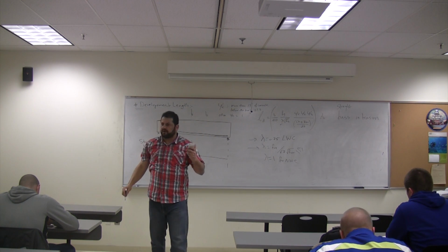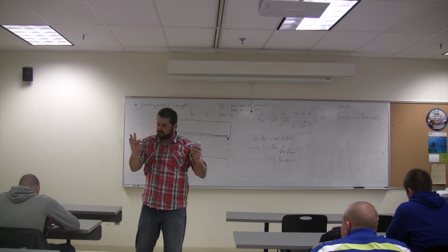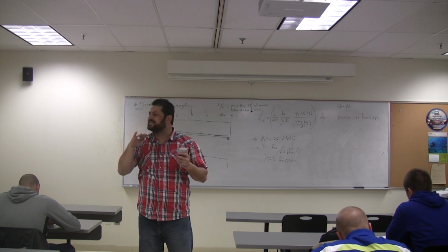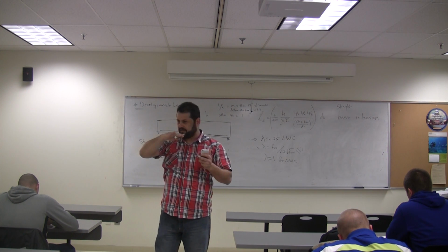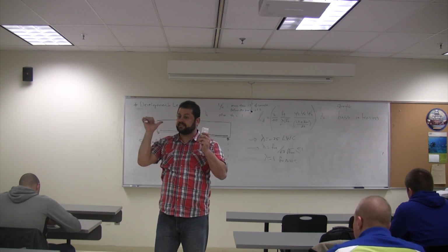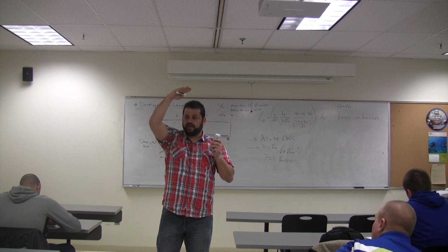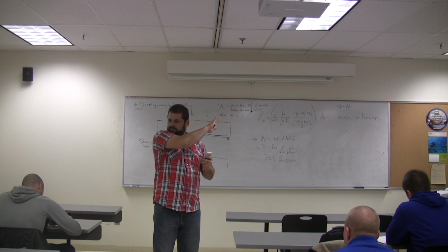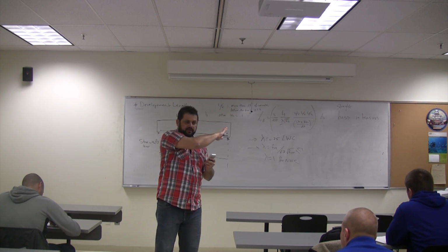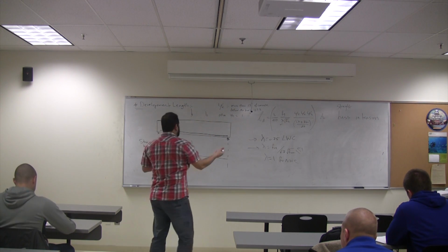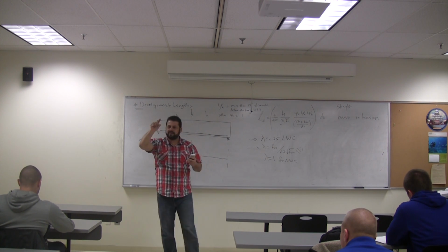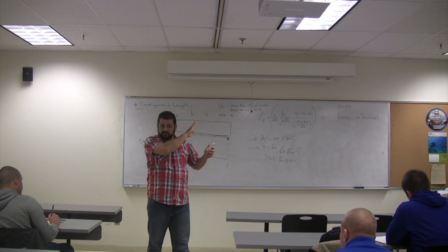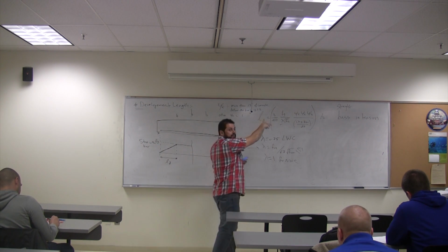So for a bar to have 1.3, first of all, it has to be a top bar. It means negative moment location. We're talking about bars in tension. Top. If the depth below that bar is 12 inch or more, psi T is 1.3. For bottom bars, regular bars at the bottom, you won't have more than 2 inch, the cover, 2.5 inch. So it will be 1. Good? So that's psi T, the T is for top, bottom.